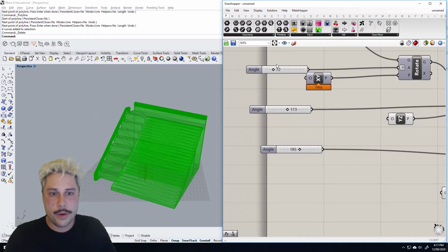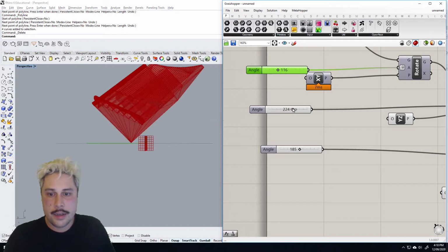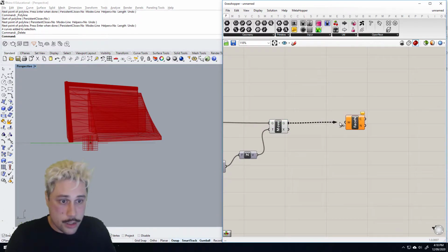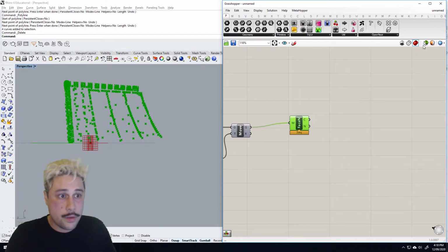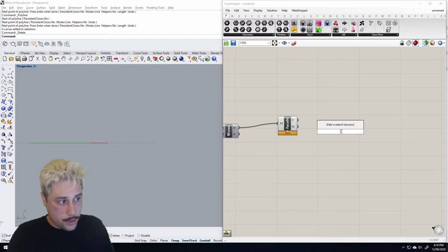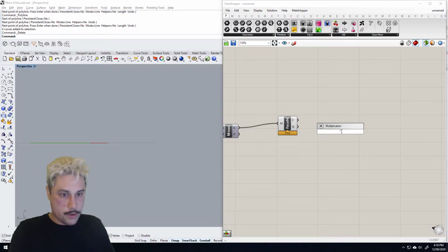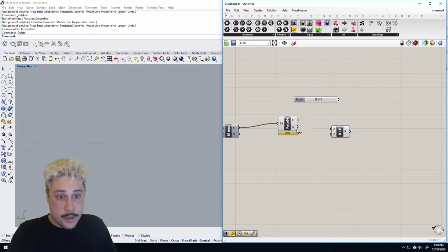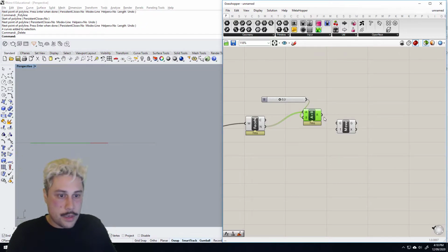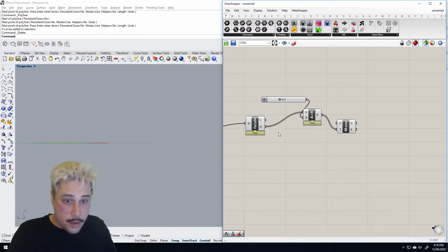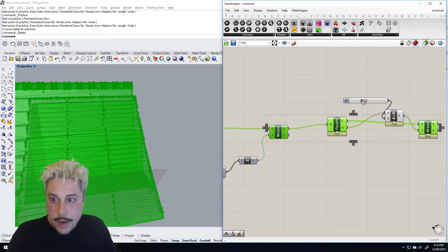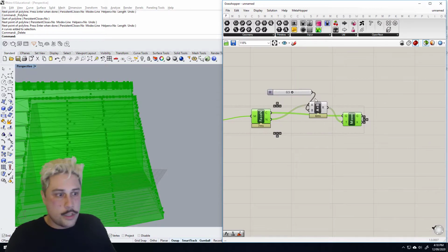So what we need to do is take this mesh that we've made. We can rotate it about all the different planes, and it'll always spit itself back right at the ground plane there. So we need to take all the face normals of this mesh, and then multiply that vector by 0.3, because we need to move them outside the mesh a little bit. So you'll see that these should be moved out ever so slightly. There you go, see that? That's just for measurement sake.